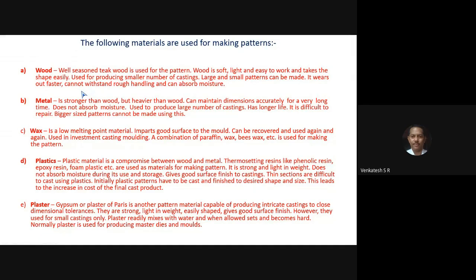The life of the metal pattern is more than the wooden one. The metal pattern will not attract moisture, and there are no chances of dimensional change if you use it for a longer period.